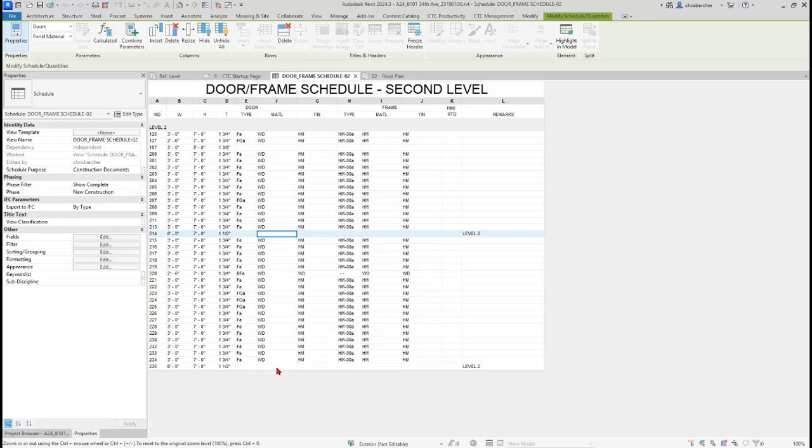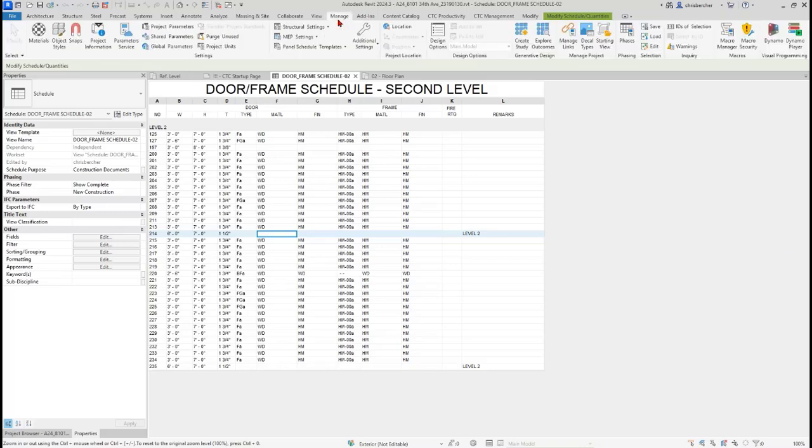But if you've got a bunch of those, like in this case, I've got a few, that could take more time than you're willing to spend on it. The other option is probably the most common option, and that is to add project parameters. Add your shared parameter to the project, tell it to apply to all categories of that type, and away we go. That happens a lot.